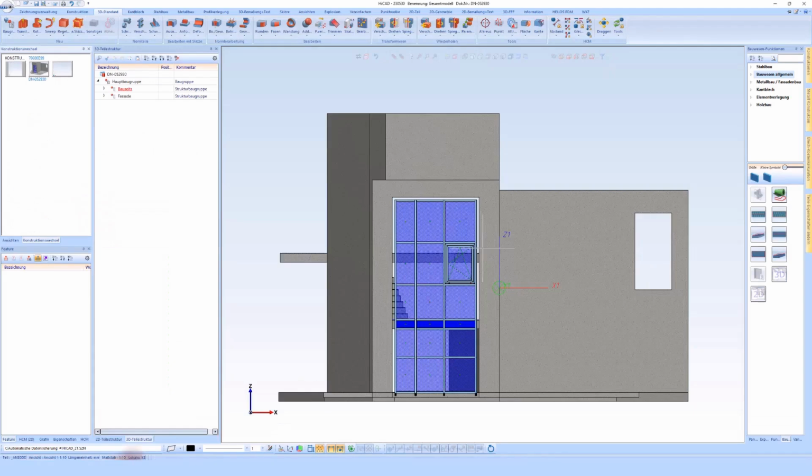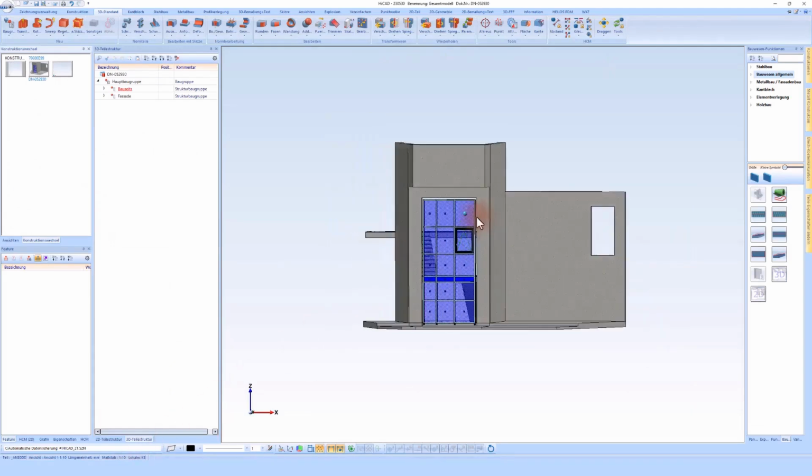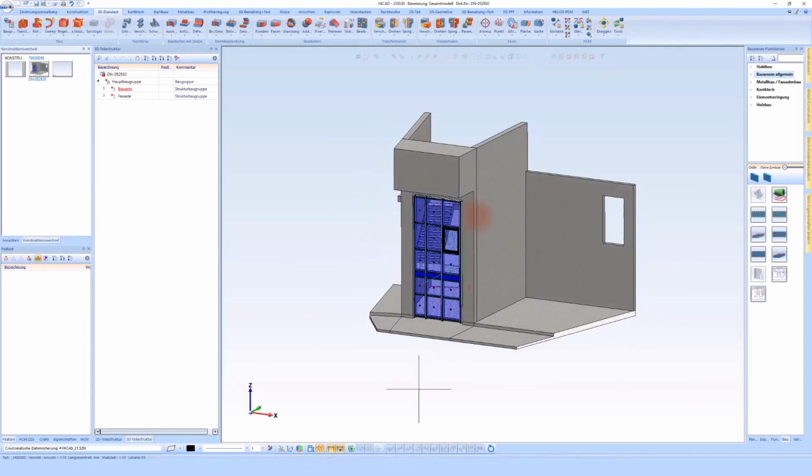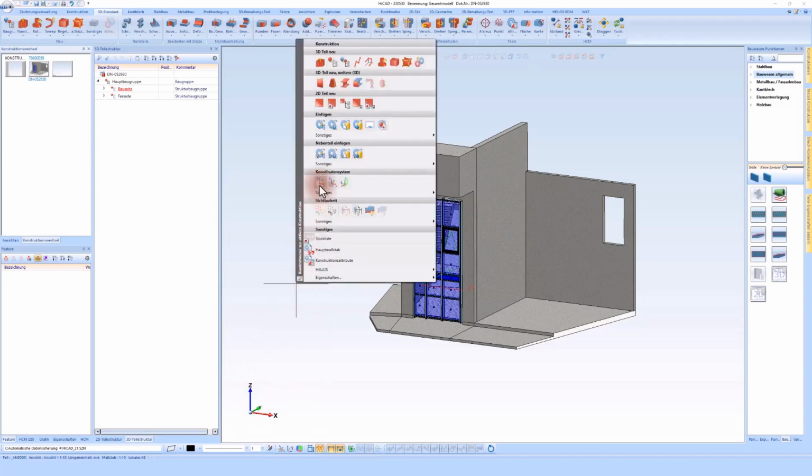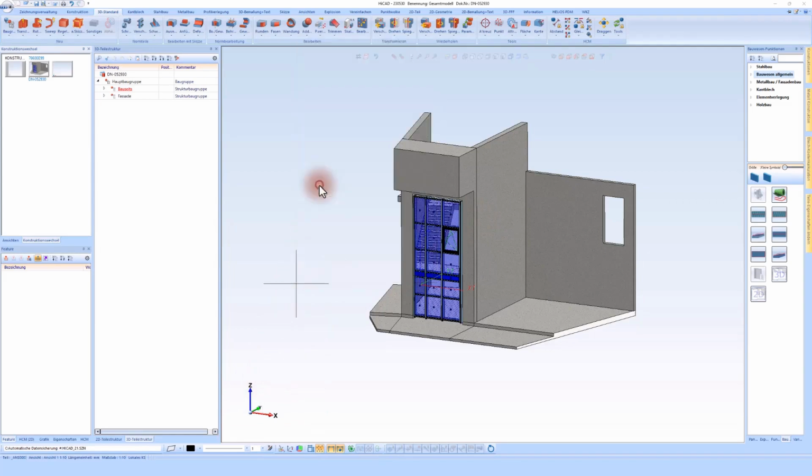Fundamentally, when working with external referencing, the most important point is always the world coordinate system. I can set this here by right-clicking on the world coordinate system. You can see it immediately on the globe. And now I can choose which parts I want to externally reference. In this case, I would like to externally reference the complete structural assembly construction kit.